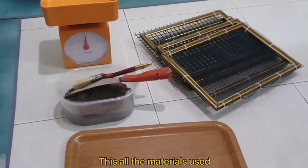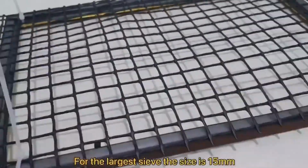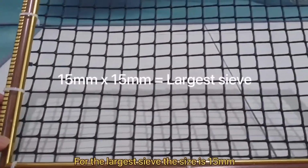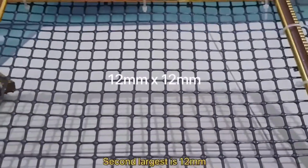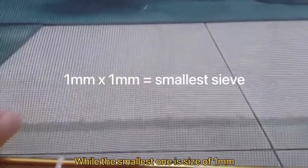This is all the material used: weighing scale, a soil sample, a tray, a pen, and DIY sieves. For the largest sieve, the size is 15 mm, the second largest is 12 mm, and the third one is 5 mm, while the smallest one is of size 1 mm.